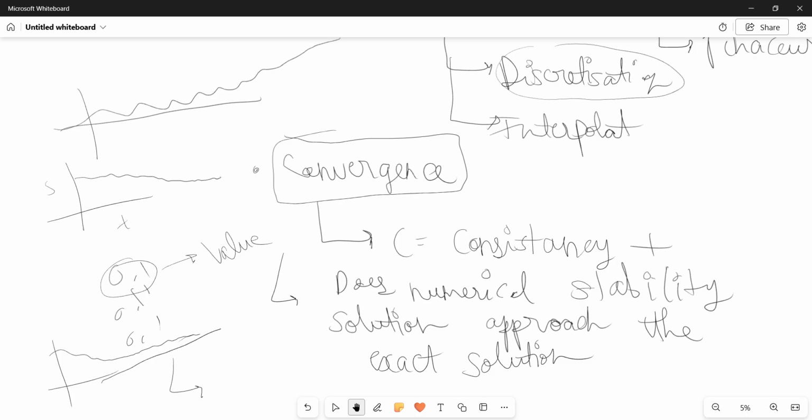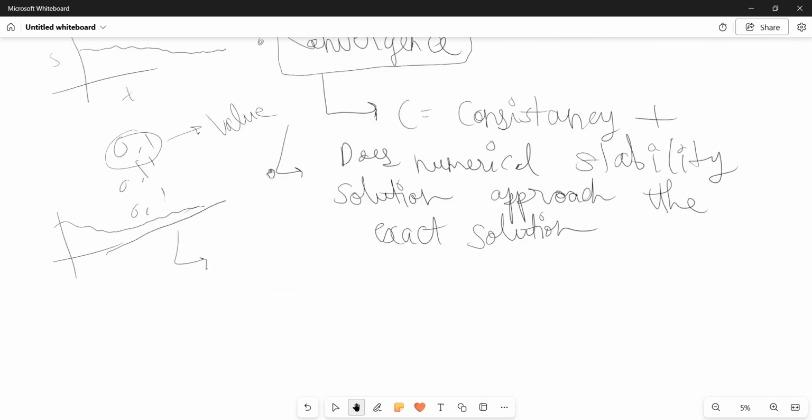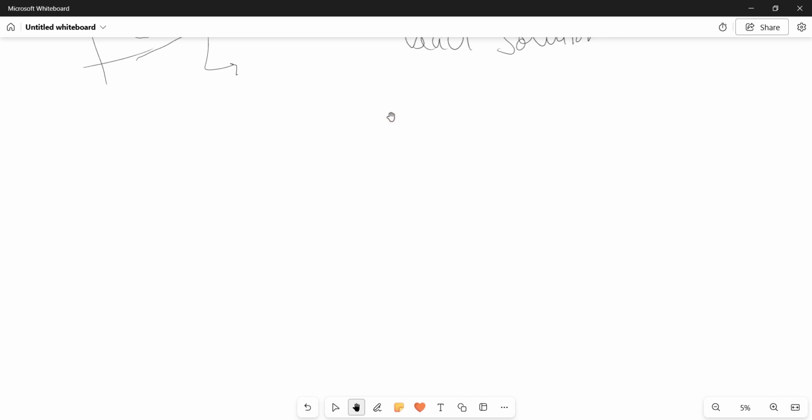Sometimes you might have done something wrong in your model, like you might have given a wrong equation. So the solution might converge, but your answer is wrong for that particular problem, right? So if you have given a wrong boundary condition, that's more like a human error, where you have given something wrong as an input.